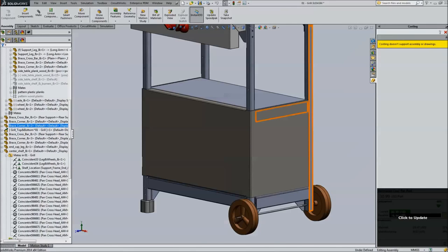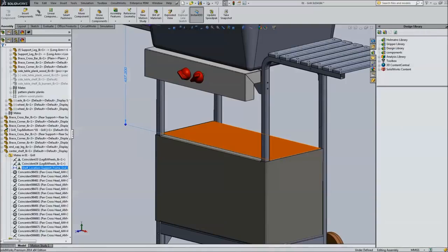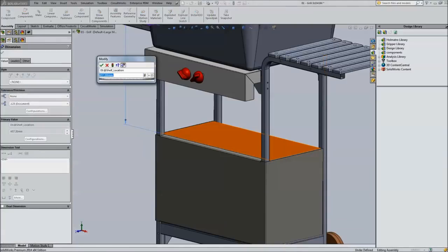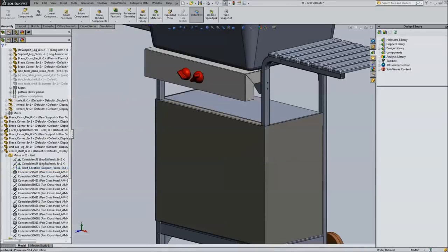But you can see now, my model went, let me just get off the costing because it's going to try and do that. If I double click here, make this 300 again, or 304.8 at 12 inches, and update it. Notice how the shelf grows again, or the skirt cover grows.